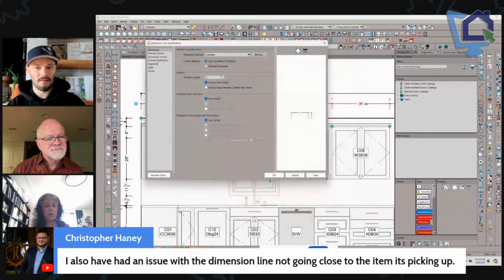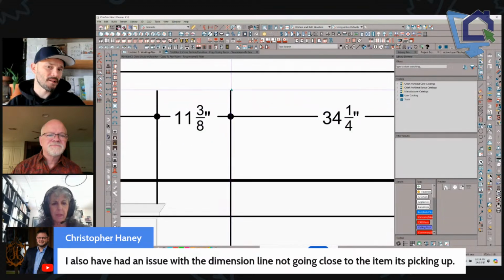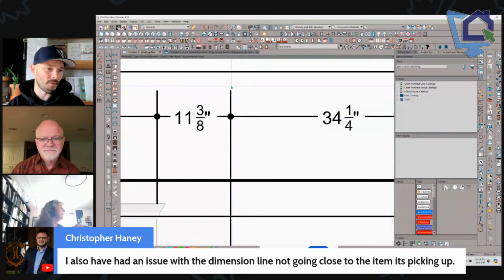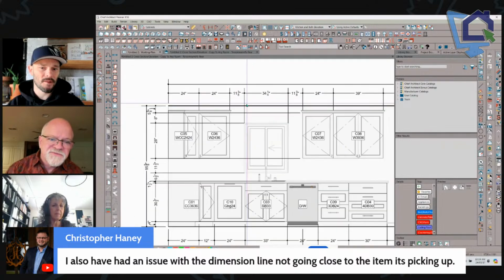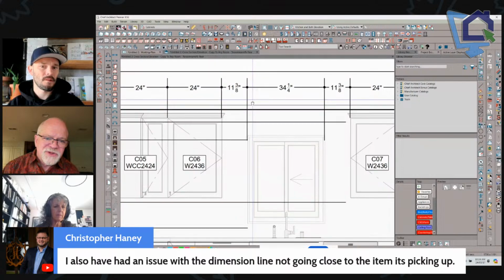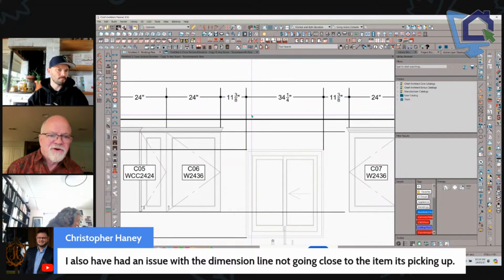Renee, can you take a look and actually show that? Yeah, so you can see here now the extension line is moving past my arrow line 4 inches. So that's what just happened with that setting. And then the other setting we did was because he's got a 7-inch separation between those two dimension lines. Even those terms, when you think about that, you're talking about several different factors that all come into play in that one drawing alone.